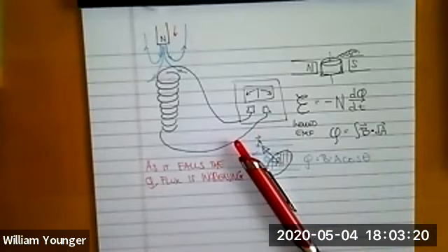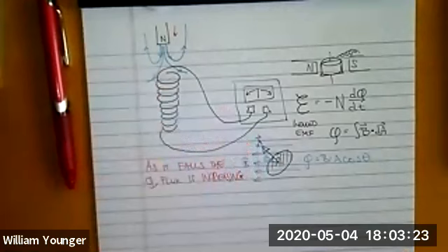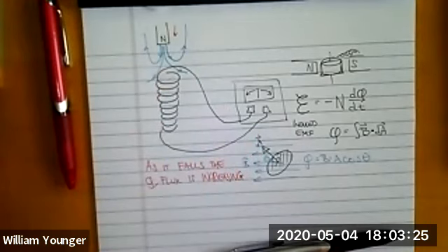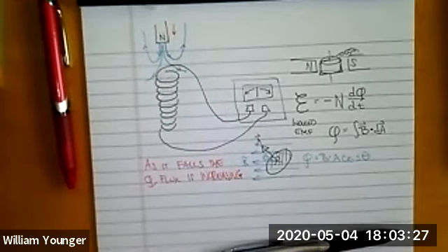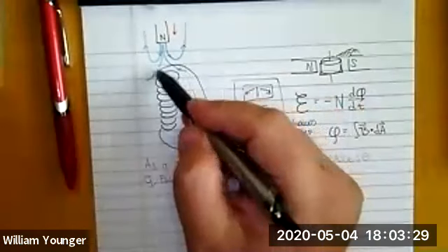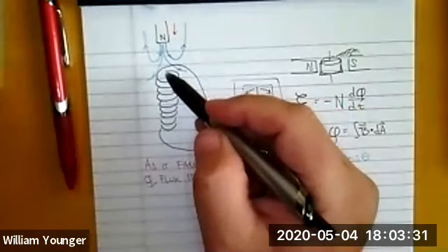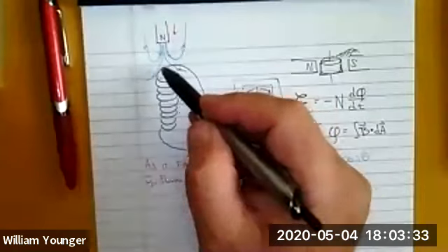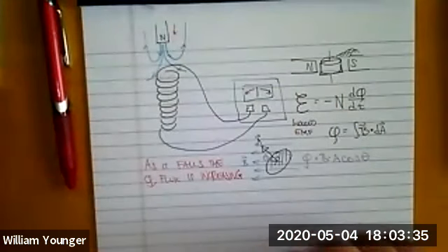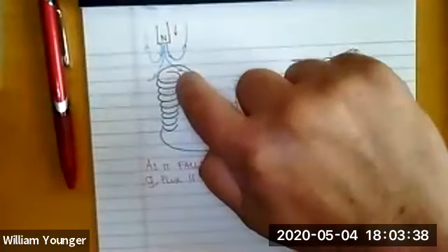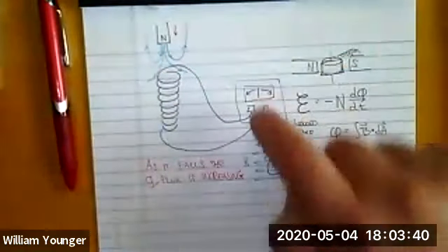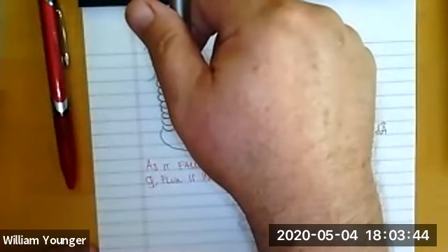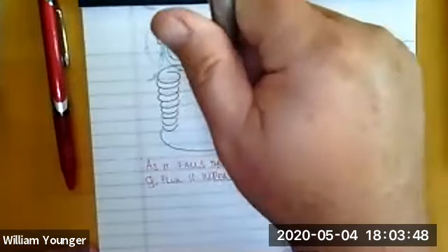Well, all a coil of wire can do to really obstruct a flux is make a current in it that creates a magnetic field. So if you imagine this little top coil, and whatever it does, all the coils will do. But if you imagine this little top coil, and let's imagine for a second the current going around this way and out over here. If we look from above, from the perspective of behind the magnet, it would look like the current's going in a clockwise direction.